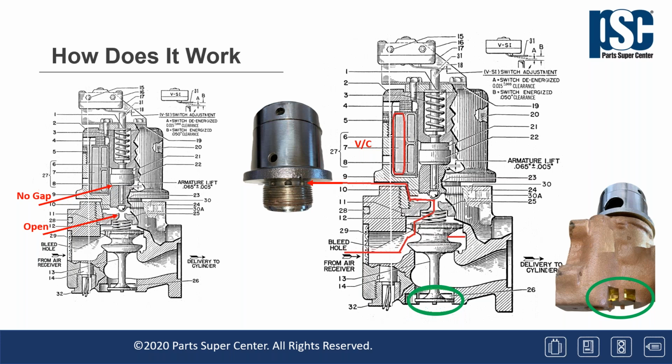When the exhaust port is open, it evacuates any air that could be trapped between the outlet side of the control valve and the cylinder and the mechanism that drives the linkage to close the breaker or open the breaker. So the piston in the lower valve could really be called double acting. When it's in the lowered position, forced downward, the exhaust port is open and the valve itself is closed. When the piston is raised, the exhaust port is shut off and the valve is open. Let's move to the next slide to see the piston and the valve body move to the open position.